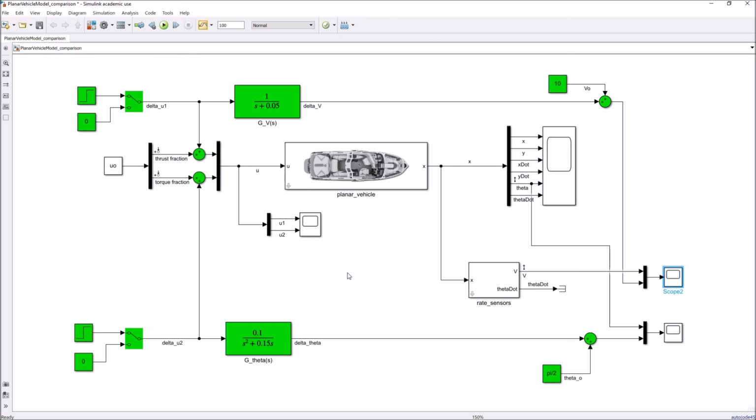Now, the next step in the process, now that we have these linear systems, is to build a controller using all of our linear system theory. The nice thing about these linear transfer functions, or the linear state space representation, is that all of the tools we built up can be brought to bear on this problem. We can do root locus, full state feedback, LQR, or any number of other control architectures, have guaranteed performance for the linear system, and then try to port that controller to control the nonlinear system.